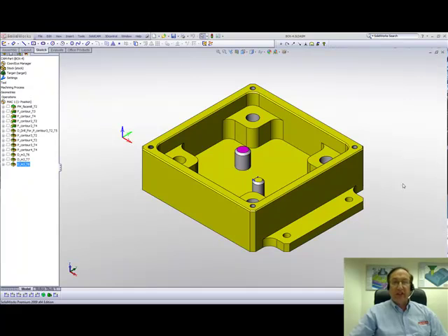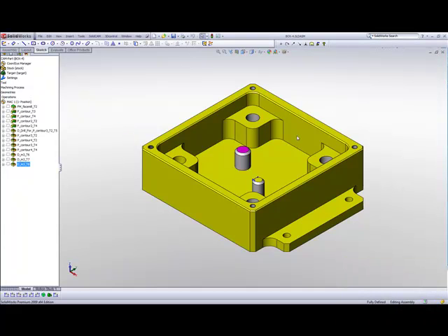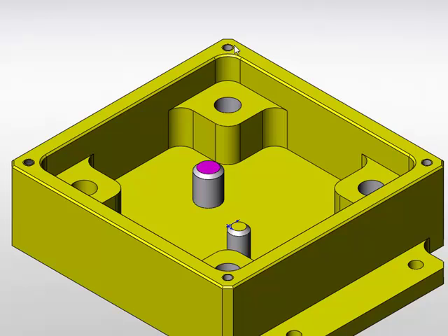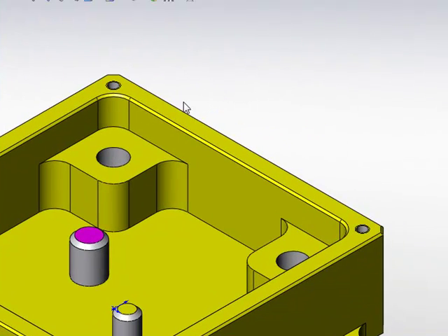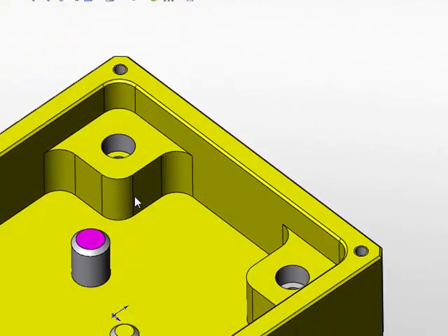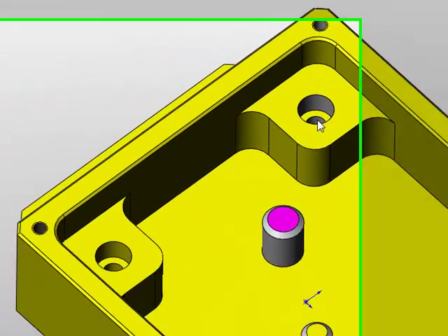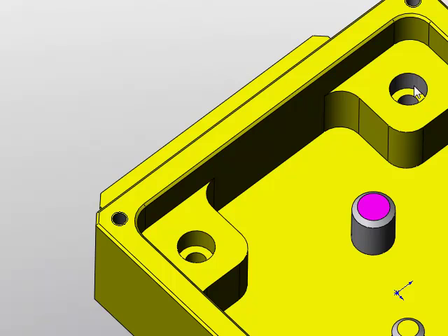on drill machining. In my previous lesson, we drilled out these M3 holes, and now what I'd like to do is work on these holes over here, which, as you can see, are counterbore holes that we have to do with two different diameters.